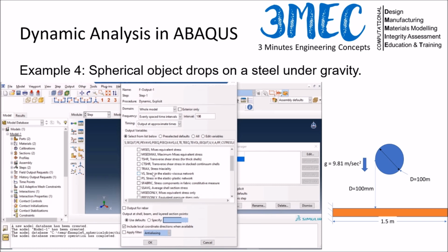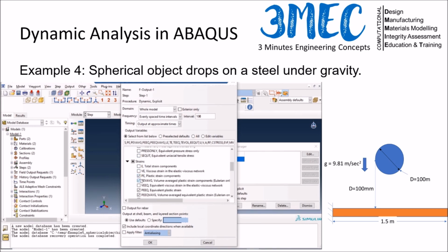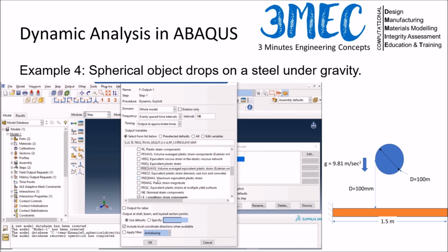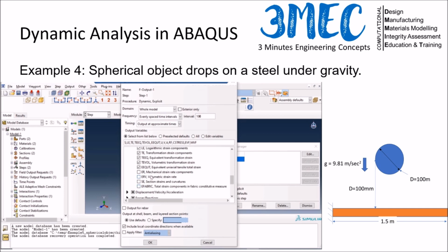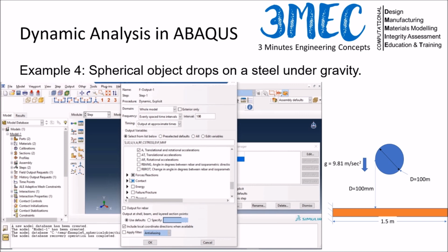What else you can do is remove some of the variables which are not needed in an elastic analysis. So I'm checking which is not required or which will not be outputted, and I'm just removing those. In this case, there is no plasticity, so we can remove those. They would not be written in any case, but just to avoid it anyway. You can play around with all these things to reduce the file sizes, because file reading and writing also takes time and will increase the overall computational time of the job itself. So that's what I'm doing here.